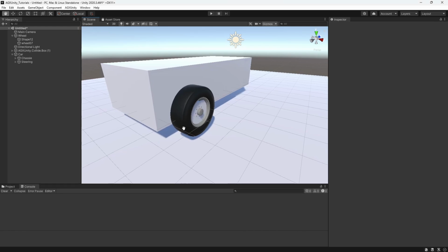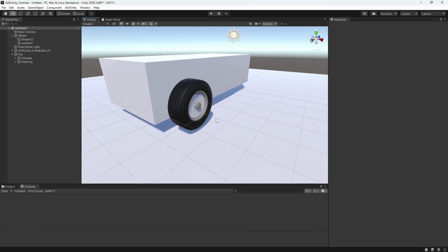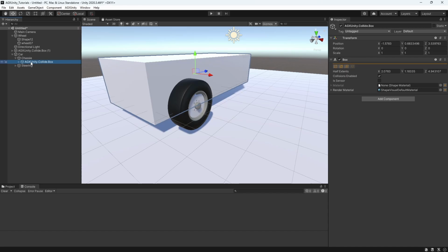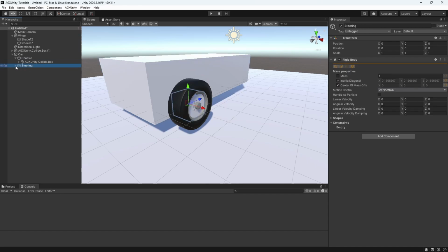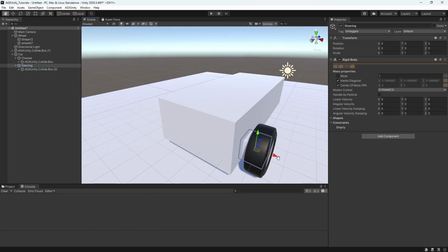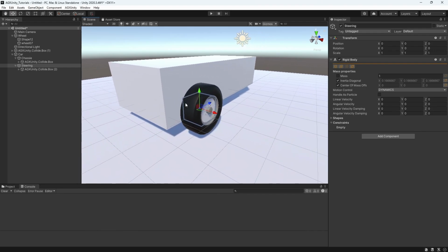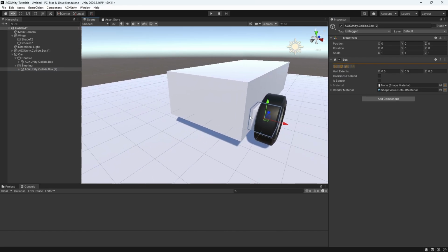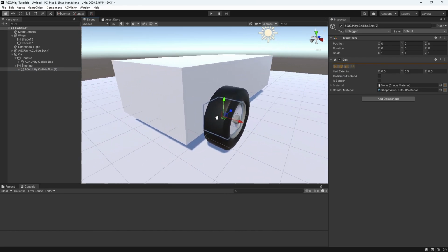Now, as an exercise with constraints, we're going to try to build a small, simple car using a hinge and something called a cylindrical joint. What we can see here is that we have one rigid body, which is the chassis, just a box, and we set the mass to 2 ton. And it has a box of a certain size. We also have something called steering, which is also a rigid body and it has some mass, 1 kilo here, and that's defined by this box here. Now, we don't want this box to collide with anything, so we disable the collision for that because it's not relevant. We only need the rigid body part.